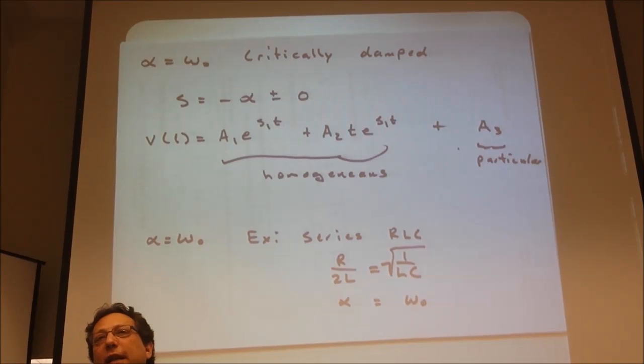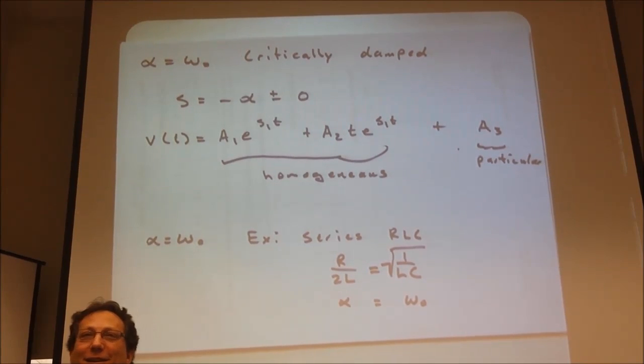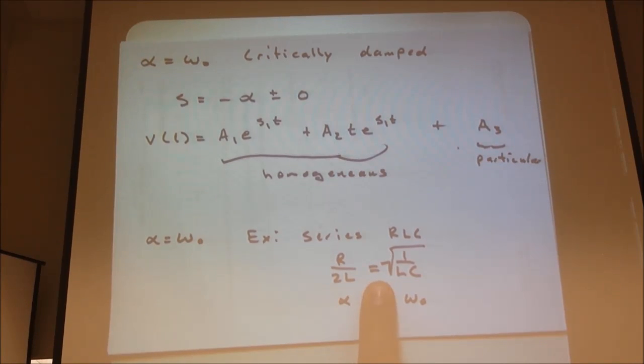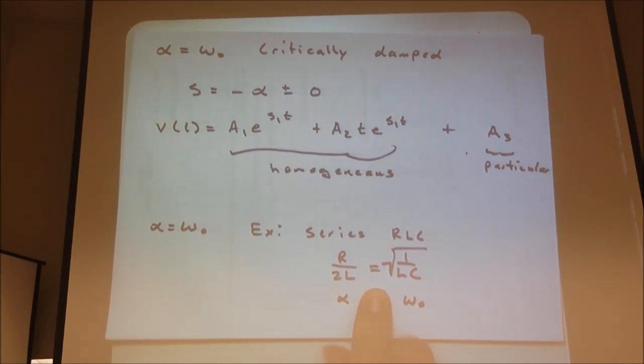What is the critically damped case? Is this real? Well, on paper it's real. But can you really match up an R, an L, and a C so that they're equal? I mean, really? It gets a little hotter, your R changes. All right, not a lot. Maybe only in the 8th digit, but it still changes.